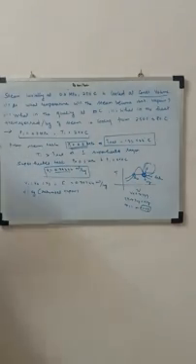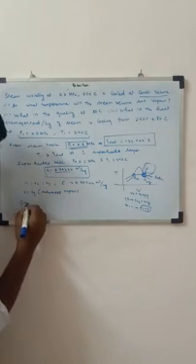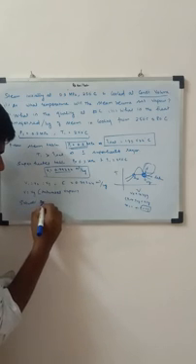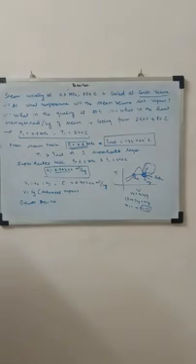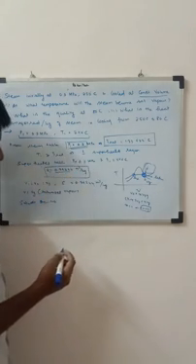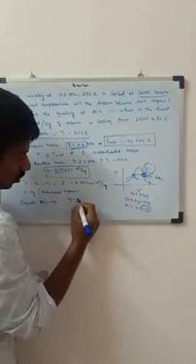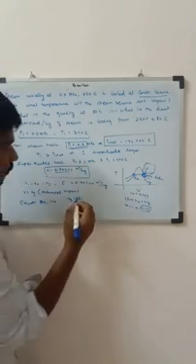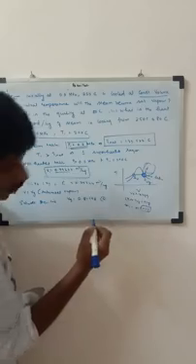So let's go to the steam table, the saturated steam table. For the given pressure, let's list down the values of Vg. Let's say 0.3 megapascal. When we go to the saturated steam table, we see the Vg value is equal to 0.81598 at 123 degrees.